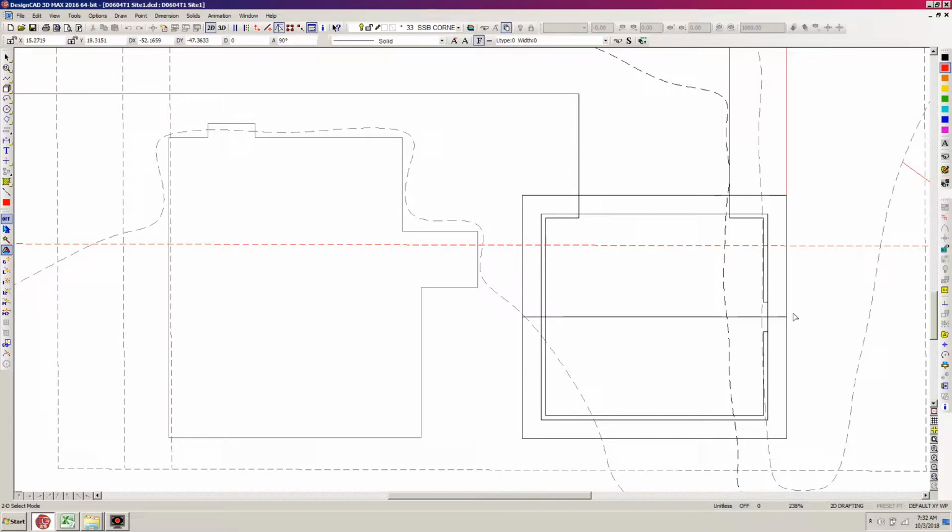Other option would be to bring the stair out here on the other end of the garage. It's a little longer walk, so let me see. I'm going to hit B for vector and just click on this corner, right click, and then gravity move using the comma on this corner, and I can see that I'm 6 point along the x-axis. 6 point is right up here. Gravity move again. 6.7037 feet, so a little over 6'8". I can put a stair right along here, but the problem with that is that it's going to really restrict access between missing the stair, avoiding the stair to get around this side of the house.